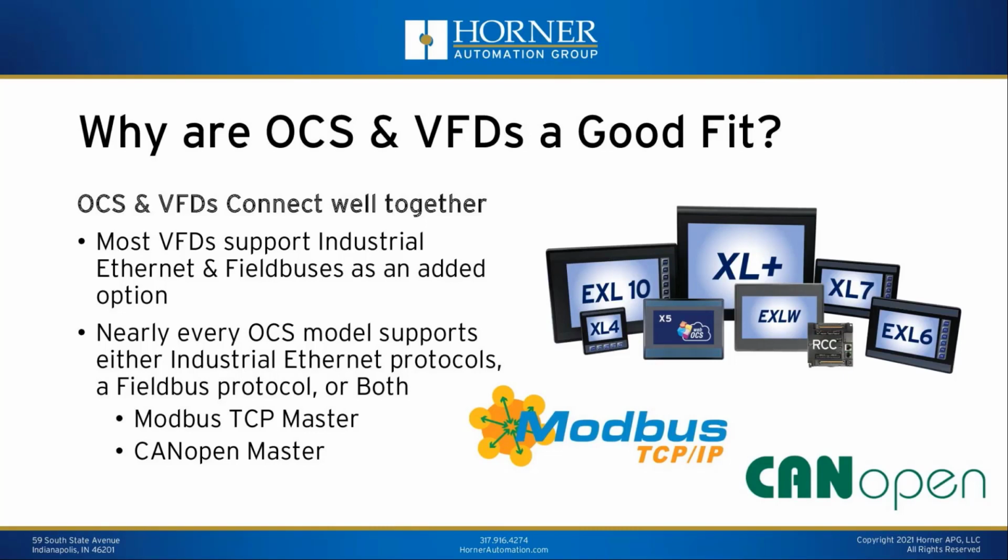There are certainly some advantages to Modbus TCP, for instance, which is a little bit easier to work with than Modbus 485. And CANopen has some advantages in terms of communications rate as well as synchronization functions that you won't necessarily find with a typical serial communications protocol.